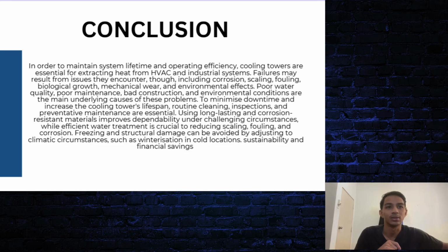To minimize downtime and increase the cooling tower's lifespan, routine cleaning, inspections and preventative maintenance are essential. Using long-lasting and corrosion resistant materials improves dependability under challenging circumstances, while efficient water treatment is crucial to reducing scaling, fouling, and corrosion.